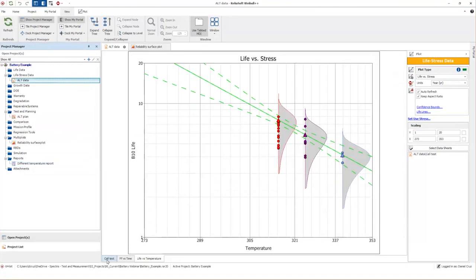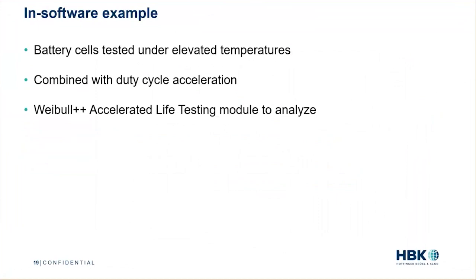So this is just one test, right? Realistically, we're going to have multiple failure modes. We're going to have multiple tests that we run, and we've got our battery pack. We've got perhaps cycle aging, calendar aging, mechanical failure, cooling system failure, etc. And using these tools, we can get a life model that tells us the probability of failure for any of these failure modes at our time of interest, 8 years or 100,000 miles. So that's already a huge advantage, right? Now we go from a single number to a probability that translates more directly into costs and intelligent engineering decisions.